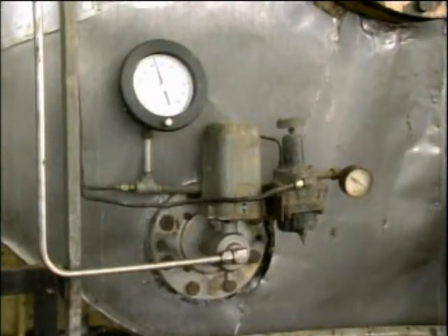Pressure elements such as Bourdon tubes, bellows, and diaphragms all convert applied pressure to mechanical motion. That mechanical motion is often transferred directly to a pointer mechanism, which indicates changes in pressure on some type of scale. But sometimes, pressure indications need to be sent to other devices in remote locations, such as a recorder located in a control room. One device that's used for this purpose is a pressure transmitter.